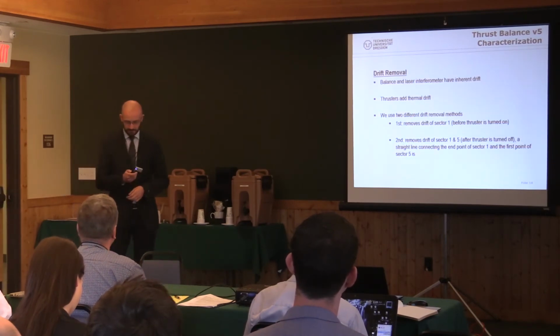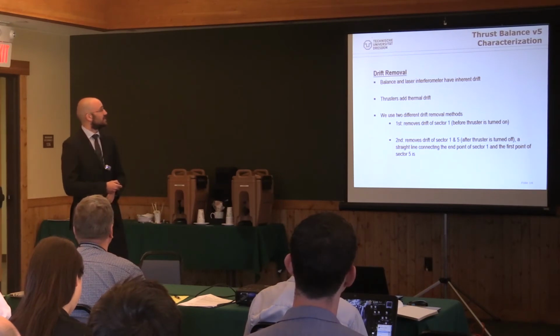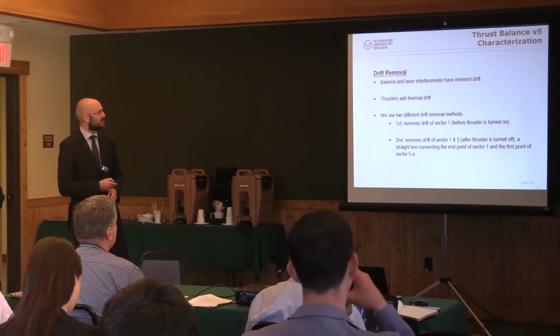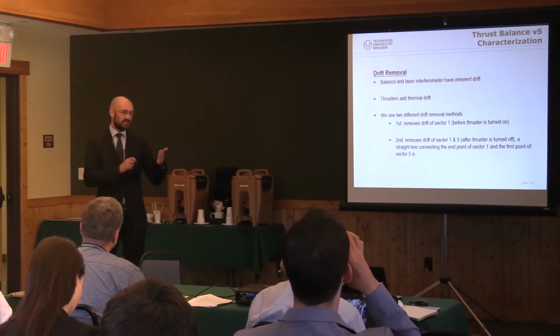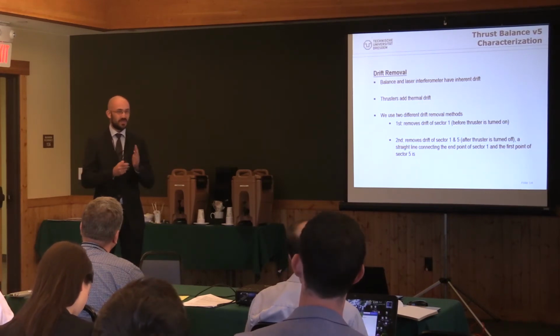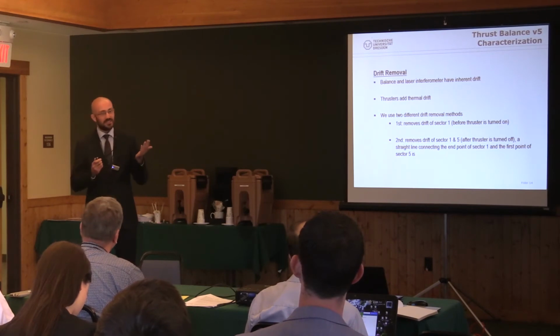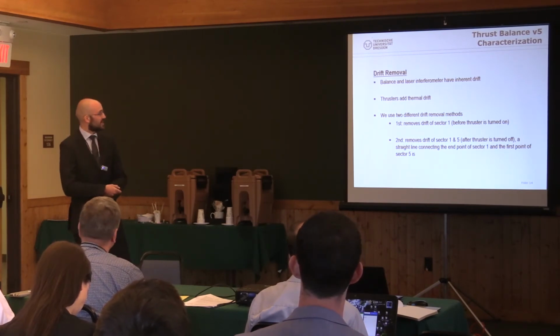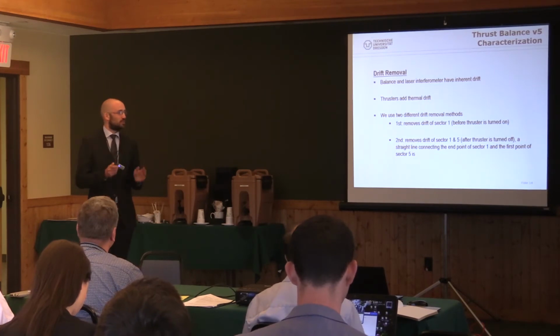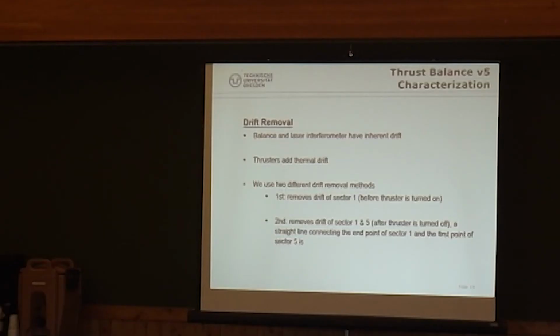So the other thing, we saw that our laser interferometer and also our balance have an inherent drift. For the laser interferometer, I had a fixed position and measured the displacement overnight, so there should have been no displacement, but there was a slight drift, so it has an inherent drift. And other drifts: if you heat up the thrusters, you get thermal events like Jamie already told you. So to look at our measurements, we have all the individual ones, and then we have a procedure to remove drift from these measurements.